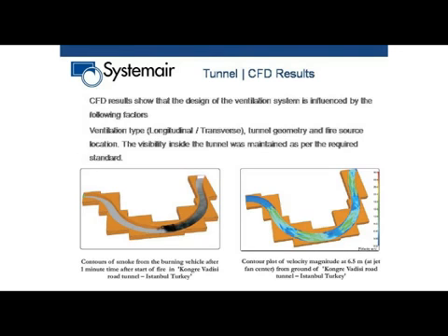We had first put all these fans in one line, but because of that the smoke was coming back, and once we did this final design, this one here, we put two fans in the same line, one after another, then the system worked really well. There was no backlayering. It's a unidirectional tunnel. We have to make sure that no backlayering of the smoke happens. The smoke doesn't come back.